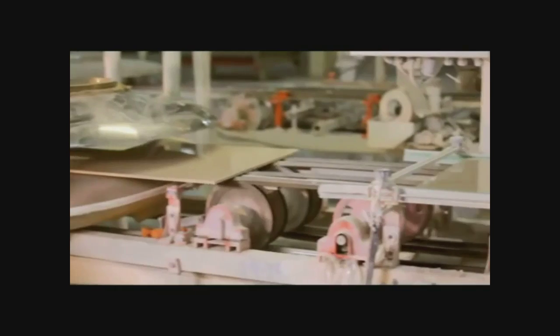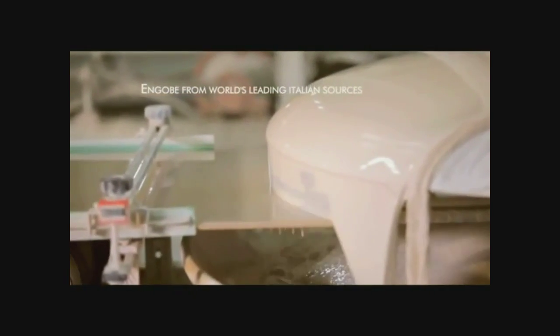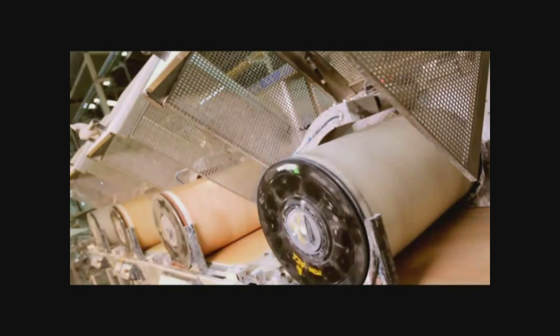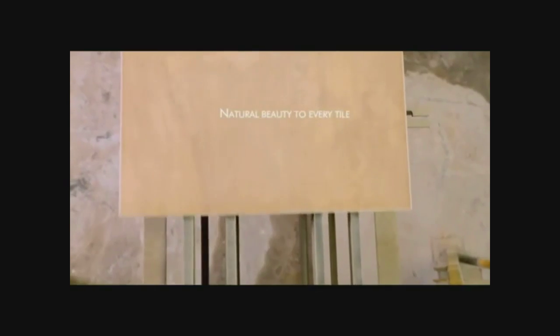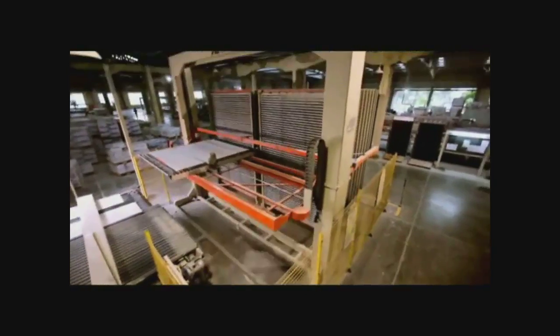The next step in the tile's journey is the engobe application. Sourced from leading Italian sources, the engobe and glaze are poured over the tile in succession, preparing them for the magic of the roto printer. A special series of 4 coloring drums operated by a sophisticated computer program. The roto printer gives every tile a unique color and design, one of the key factors behind the variety of patterns and the nature-like beauty of Nitco tiles. These printed raw tiles are now ready for heat treatment.